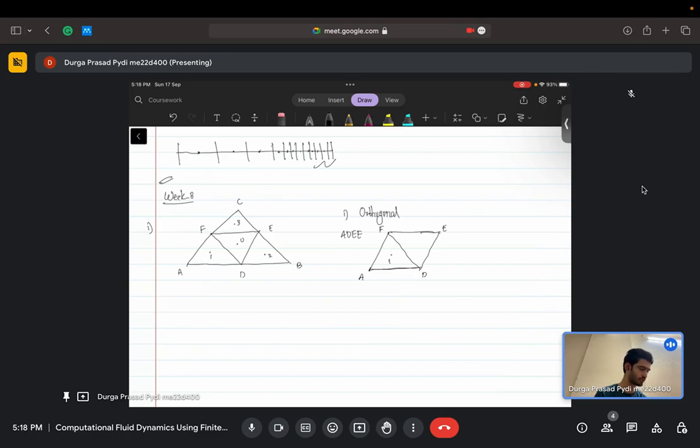So the cell centroid is 1 and the cell centroid is 0. Along the face, you take the face normal. So this is my area vector, and then you consider the line joining the cell centroids of both the cells. Say this is R bar. You consider the mesh orthogonal if A bar is parallel to R bar. So if each face normal vector is parallel to the line joining the cell centroids, then those particular cells are considered orthogonal.